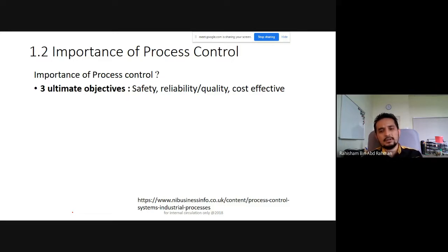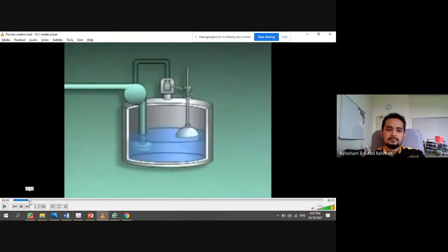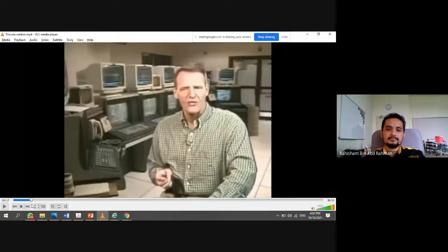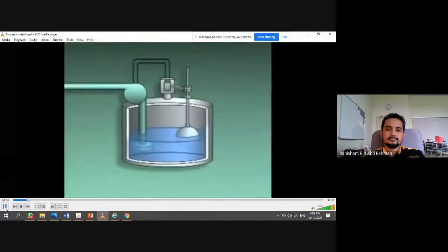what the instrumentation and process control are, particularly in the oil and gas. If you look carefully at the end of the video just now, we did mention that with proportional control, we'll then turn the pump on or off. But even though the water will be maintained at a more constant level, the pump will turn on and off more frequently.